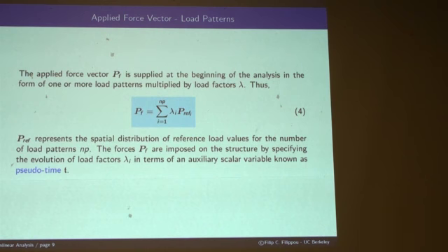A reinforced concrete column. I'm going to apply an axial force, constant. I'm going to apply a horizontal force, increment it linearly, and then I'm going to apply another horizontal force and increment it linearly, while keeping this one constant. And then I'm going to reverse this force, okay? That's a situation which is quite common if you are going to do it under force control, so with applied forces. That's a situation that is common in analysis.